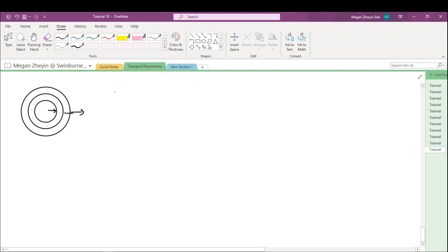The rate of diffusion in at R is given by 4 pi R squared J at R, since this is a sphere, minus 4 pi R squared J at R plus delta R, minus k C_P 4 pi R squared delta R rho_P equals 0. This last term is your rate of removal of the toxic gas.